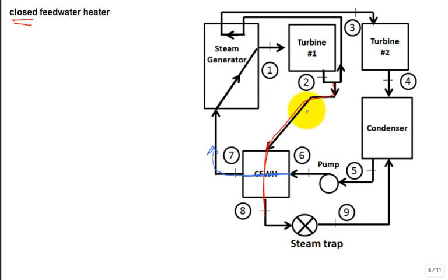So the mass flow rate that comes in to feed the closed feed water heater is what comes out the bottom, going down through what we call this steam trap. Okay? So what happens is, think about this. Usually this is some intermediate pressure. Think of about 1 MPa pressure, that's a number I've been throwing around.